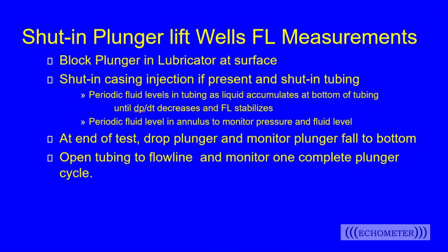And then at the end of the test, we'll drop our plunger and monitor the plunger fall to the bottom. And we'll open the tubing to the flow line. And we'd like to use our plunger lift software to monitor one complete plunger cycle. So oftentimes, if you know you're going to be shut down for an extended period of time, again, it might be good to do a baseline monitoring of the plunger cycle before you shut the well in.